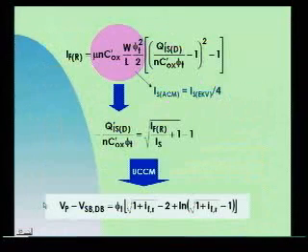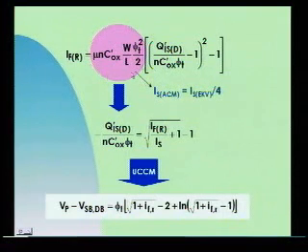Okay, and I did this here, and so here appears a normalization current, a specific current that is almost the same as in the EKV model. The only difference is a factor of 4. The ACM one is 4 times smaller than the EKV, but it also has the technological and the geometric information of the device.